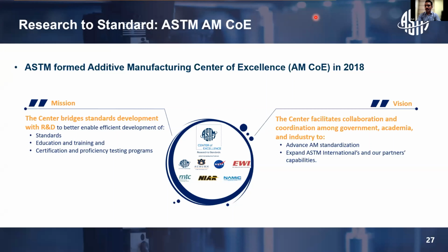Yes. So for polymeric, when it comes to polymer testing, it's completely different. The testing of additively manufactured polymers is different from testing of conventional polymers, primarily because you are talking about FDM, primarily because of the way in which the material is printed. So you cannot simply use the conventional way of testing, because your failure will not be within the gauge, and your failure will be at some other locations.